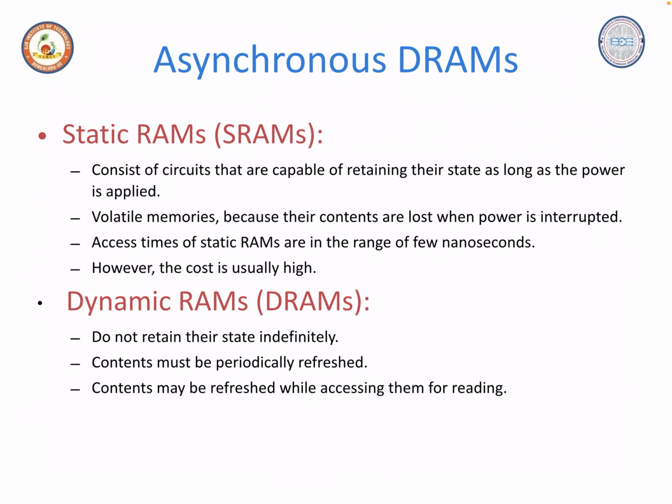The cost of the circuit is high because their cell requires several transistors, and less expensive RAMs can be implemented if simpler cells are used. However, such cells do not retain their state indefinitely for a long time. They can't retain their value, so they are called dynamic RAMs. You need a periodic refreshment in that.